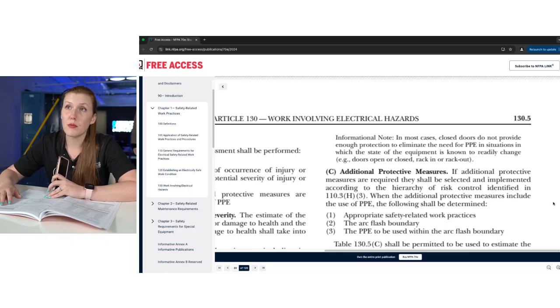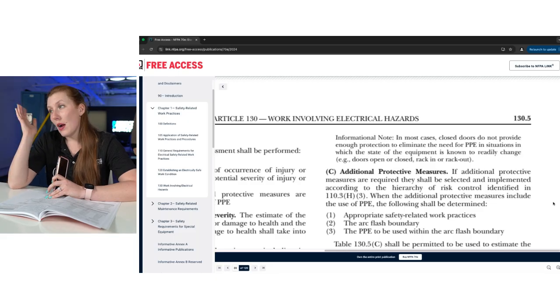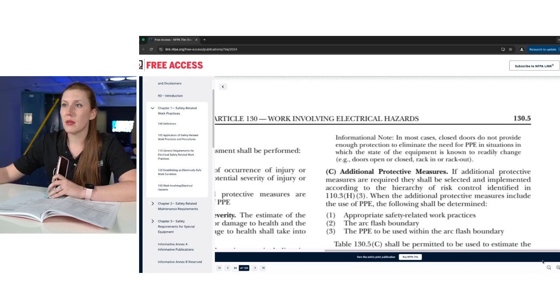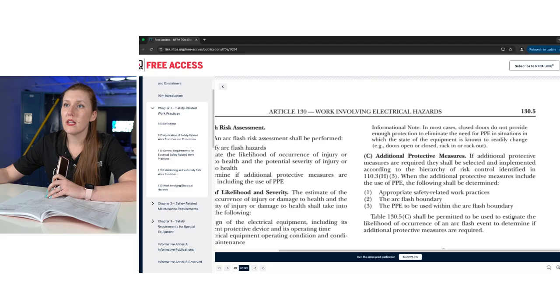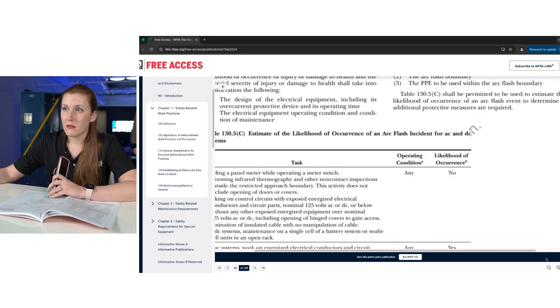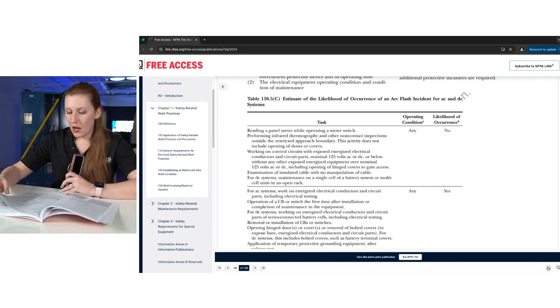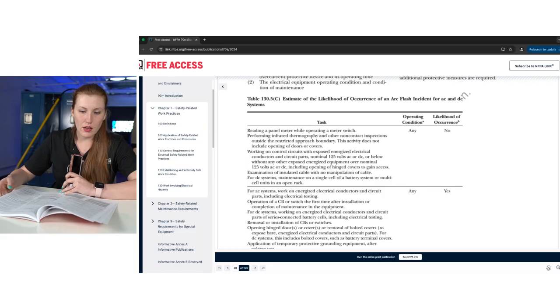So bigger one is racking in and racking out. More people understand that, and I think have been doing that already, where they suit up whenever they're racking in and racking out stuff, especially while the gear's energized, which I really wish would stop, but I know some people have to, so they suit up for that. That's another example, very, very common. But it's added in there, something to keep in mind whenever you're doing your risk assessments and determining what needs to be applied there.